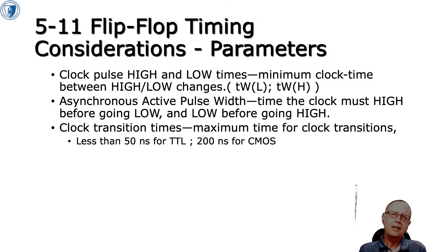When you're thinking about flip-flops, in fact logic circuits generally, you need to have various timing considerations taken into account. You need to make sure that the clock pulse high or low times are long enough for the effect to happen. Sometimes if the clock goes high really quickly and then changes back to low really quickly, then the effect won't be felt.